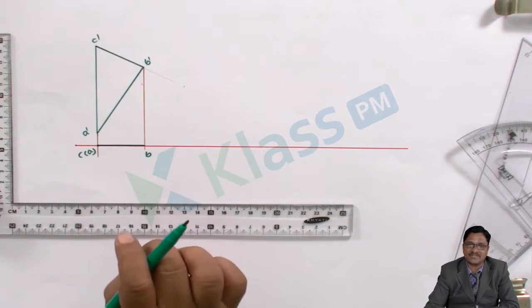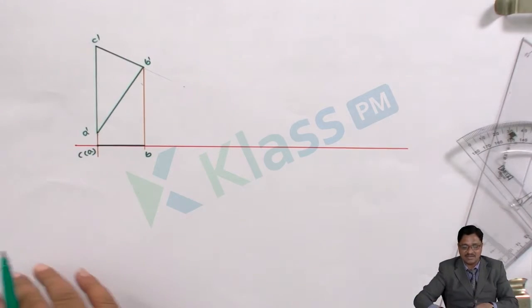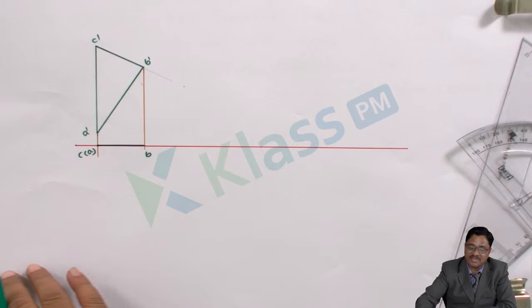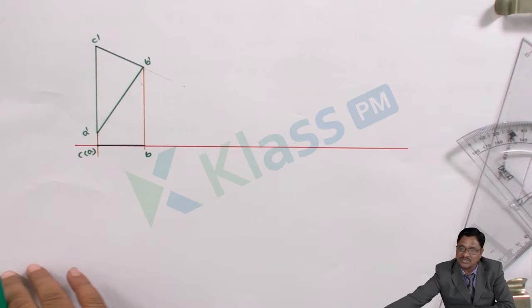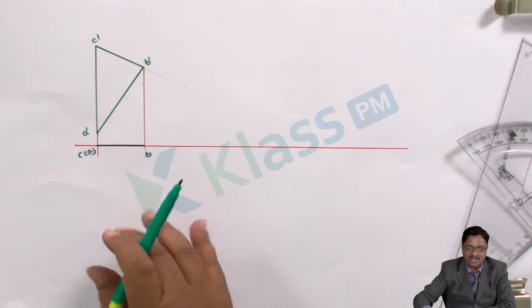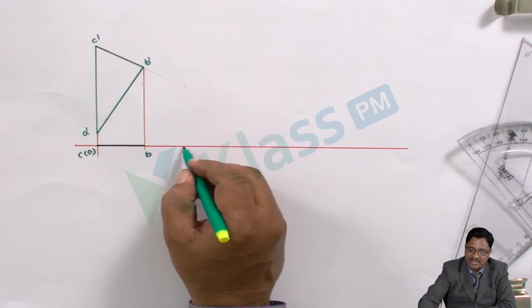So the top view has to be shifted, meaning the top view shows the details of the vertical plane. Now observe the vertical plane details from the problem. What vertical plane details are given? It is 45 degrees to the VP. The edge is in VP and it should make 45 degrees to the VP. So in the next stage, you have to satisfy that condition. For the edge resting, you have to take the two points as reference, so you have to locate them in the new location.